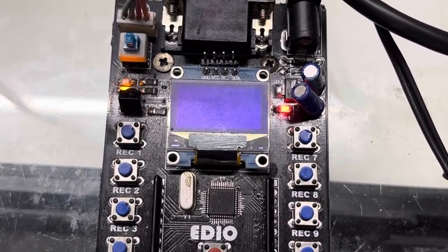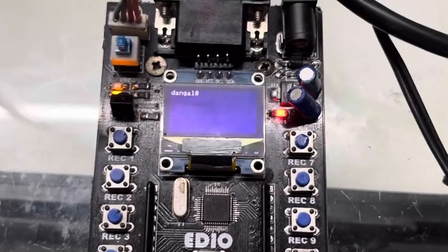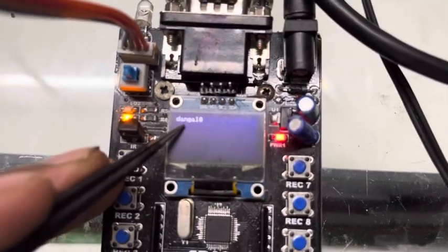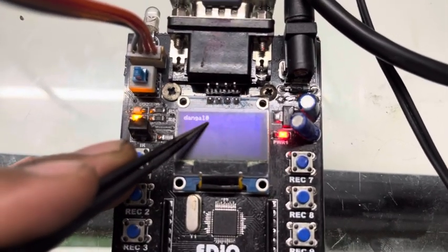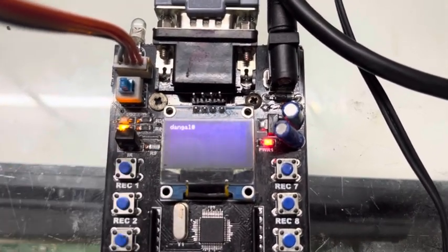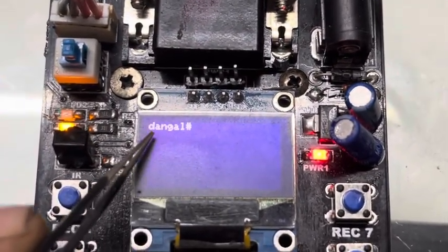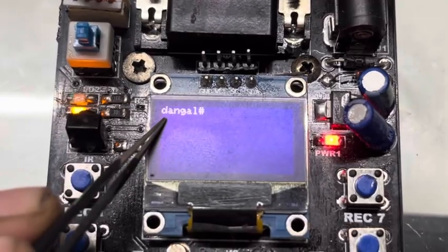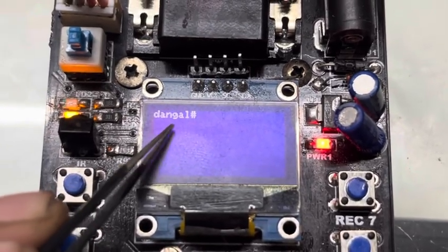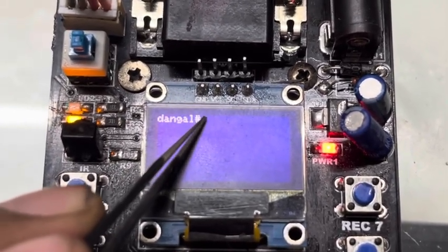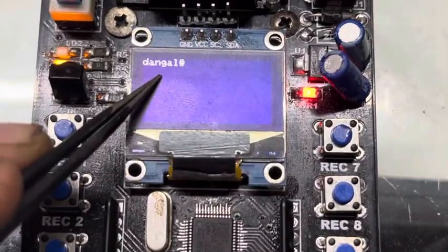Once you get this type of text with ASCII, your motherboard has entered console mode. This text will change based on the processor and the model number. The text will change, but once you get this type of ASCII, your motherboard is in console mode. Only at that time will the recovery buttons work. If the motherboard does not enter into console mode, the buttons do not work.